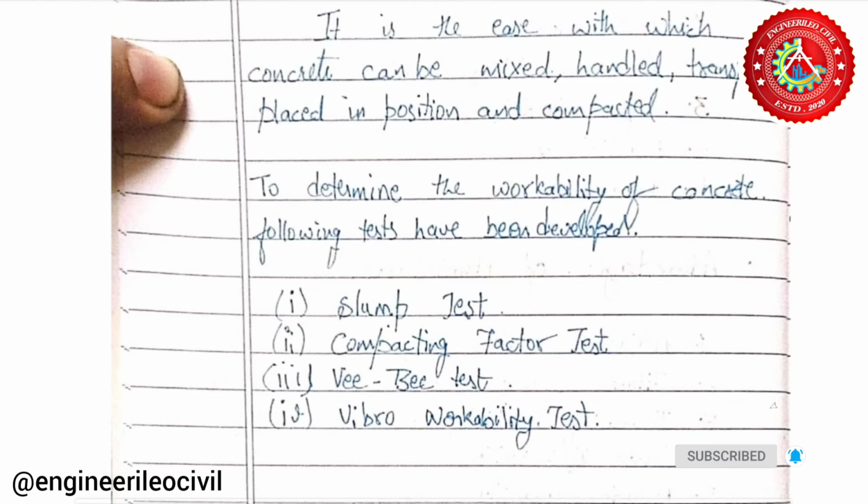The greatest factor affecting workability of concrete is the mixed amount of water. As water increases, workability also increases, but the strength decreases. Other factors are maximum size of particles, ratio of coarse and fine aggregates, particle interlocking, particle interface, and admixtures.